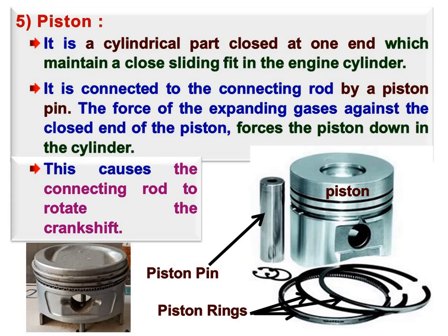So as and when burning of the fuel takes place during the power stroke, there will be expanded gases inside the combustion chamber, and those expanded gases force the crown of the piston, or the top of the piston, downward in the cylinder and transmit the power to the piston.